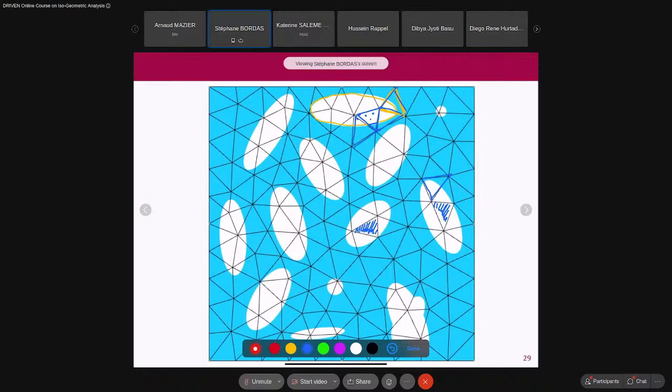But that's not sufficient, as we said last time, because if we do only that, we will have a smeared interface. If we plotted the displacement and the interface was here, and we do not use any enrichment, but instead simply use an average modulus, then inside the element we would have a linear curve, and the linear curve would have a slope which is some weighted average of E1 and E2. But the slope will be constant, which is incorrect.